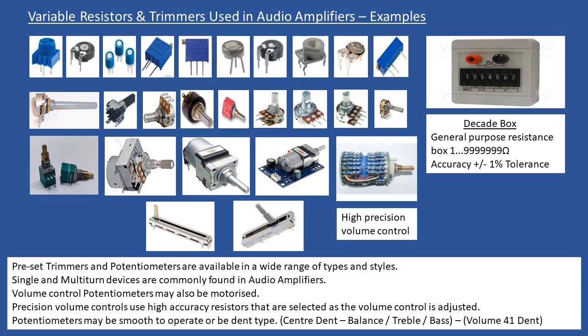But the resistance values, like the fixed resistors, will be linked to a particular series. But these trimmers, these variable resistors, can be both single turn but also multi-turn. So when I talk about multi-turn, what I'm referring to are, for example, a potentiometer or a trimmer where you can rotate up to a maximum of 10 turns, and we use these commonly in biasing circuits.